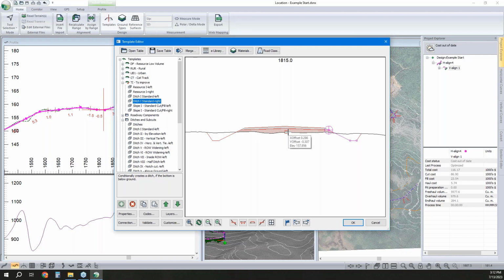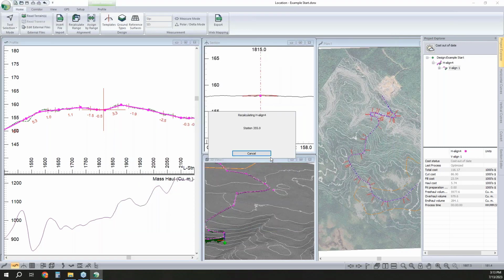and that's going to let us increase our embankment height, which is going to help with drying things out in the sun. And if we're living in a temperate climate or somewhere where it gets snow, it's also going to help with snow removal. So the snow that gets bladed off has somewhere to go. It just doesn't fill up a trench off to the side that isn't going to function. So since we're changing the template that's been applied, we'll see the changes take place for us.